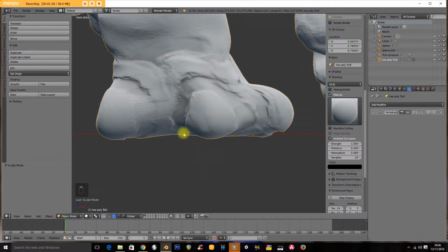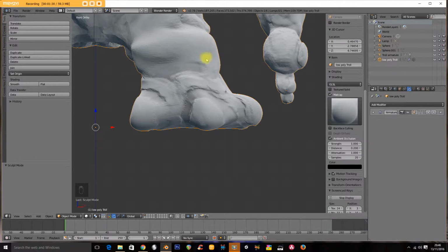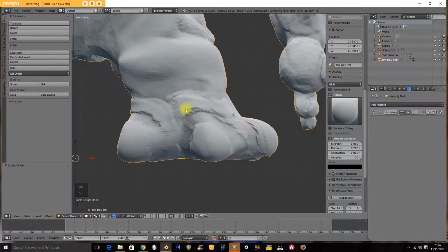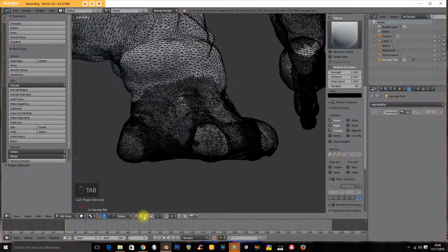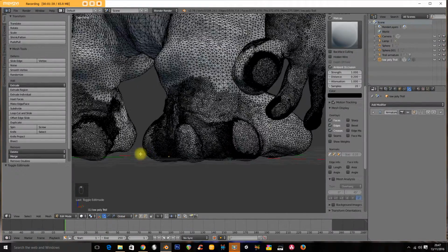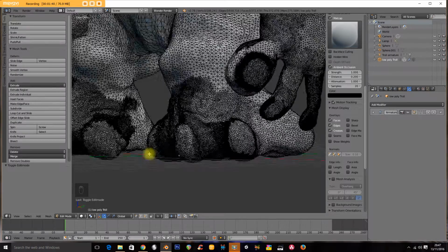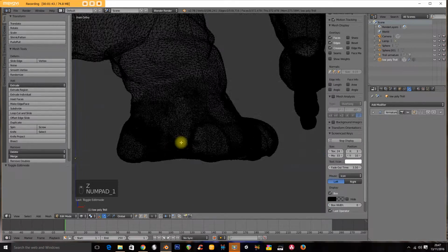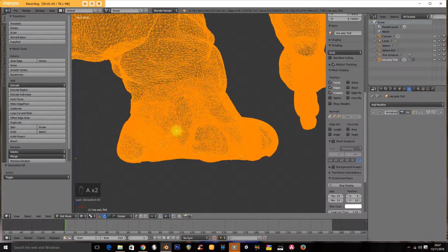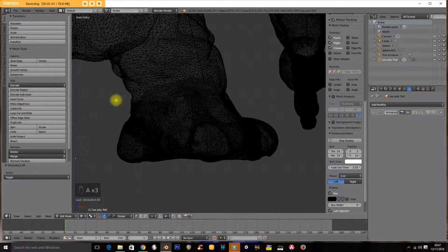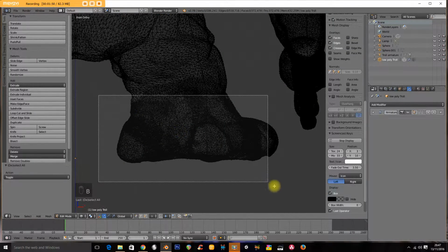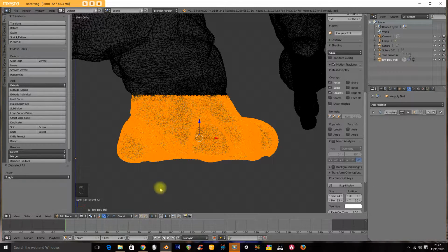And I'm going to go into edit mode, which is, I need to check, I've only 187,000 verts, so it's not too bad. So into edit mode, and I'm going to make sure I can see everything. So in wireframe, and I am going to select this here, and I don't want obviously a straight line, so I'm going to turn on proportional editing, and go G, X.